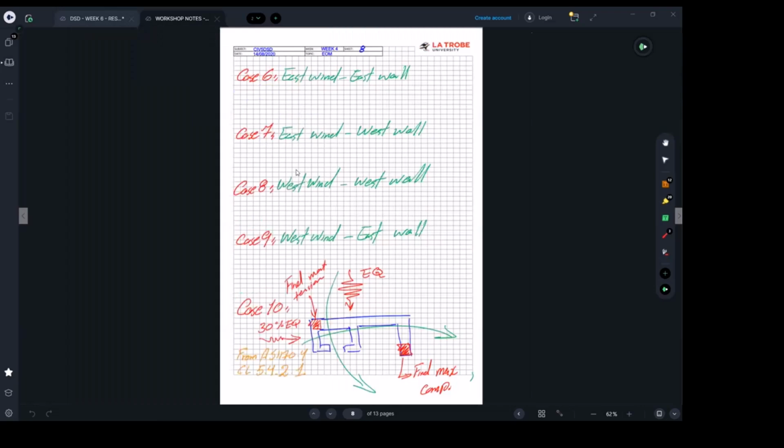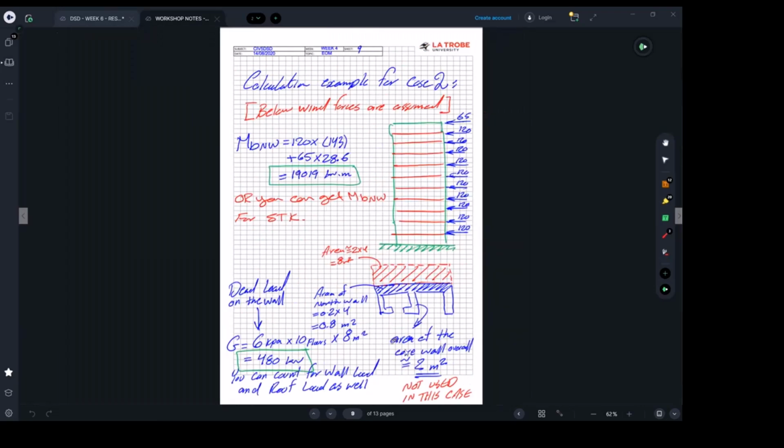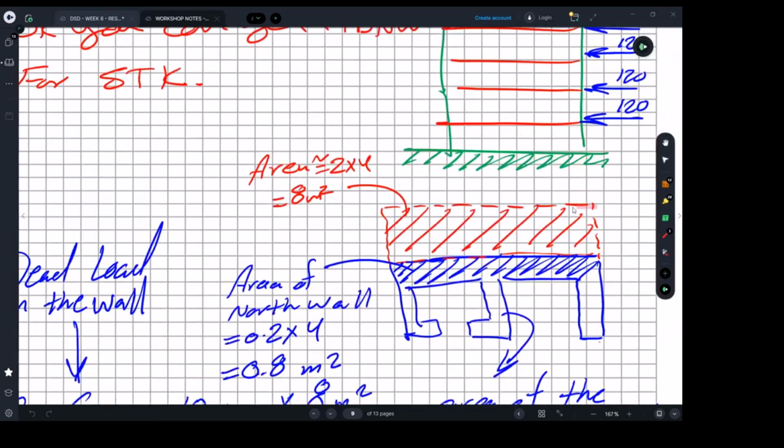So going back to where I was, my approach is to find the kilonewton value. First thing, I have the slab component pushing this wall down. So I found the area, then I'm going to multiply the area by the pressure. What's the pressure?